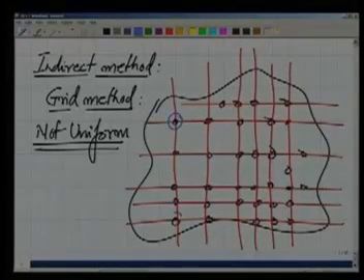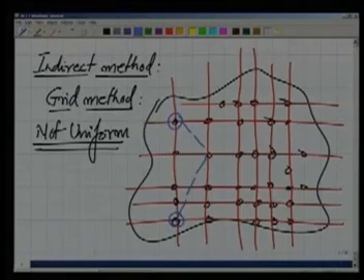We can use two theodolites, one kept here, one kept here, and in our grid design, which we have already designed, I can have the angles of intersection for all the points. For example, here this theta and this theta. So using theta 1 and theta 2 for all the points, I can locate those points there on the ground.